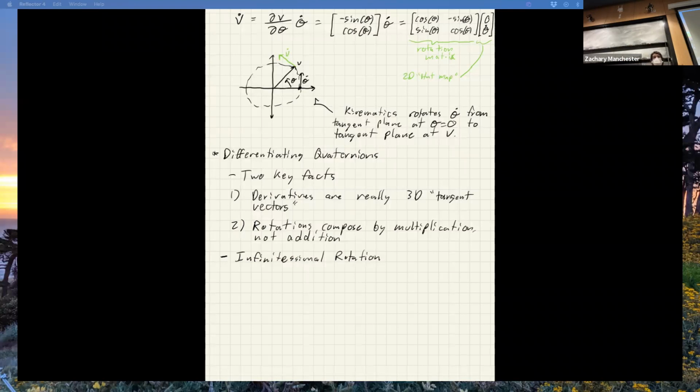So this is a very different thing, and it takes people a while to wrap their head around this. It's weird, but this is 3D spatial stuff you can think through in your head really easily. Don't get too hung up on the math. Whenever that happens, try to think about pictures. I like the roll-pitch versus pitch-roll example. Totally different, right? That's just the fact that with the matrices, or the quaternions, the order matters.